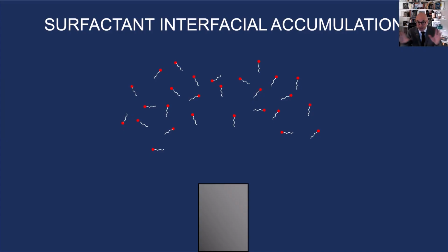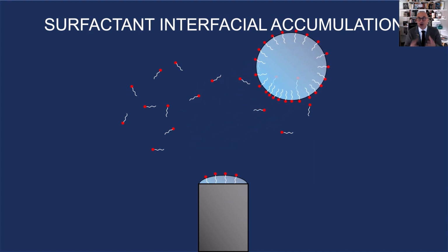The surfactants are floating about in the water, minding their business, and then the bubble interface offers a volume that is made not of water, and so the surfactants migrate right away to the surface of these bubbles. If these bubbles are fine bubbles, 2, 3, 4 millimeters, like the ones from fine pore diffusers, by the time they detach, the surfactants already reach their equilibrium concentration at the surface. So the bubble travels with this straitjacket.